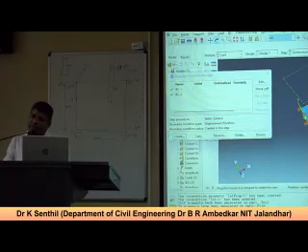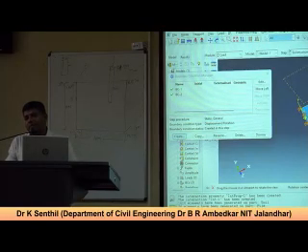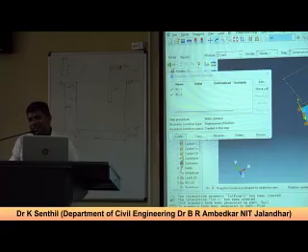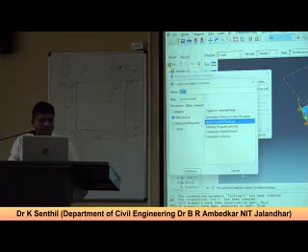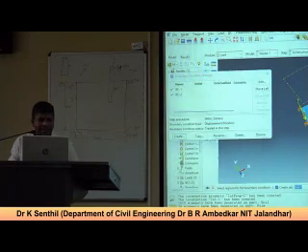No, we have already defined the mass. No, we haven't. You only defined the force. Okay, and you define it in the vertical. That is the external force coming from the superstructure. The only way you get these earthquake-related problems to get the inertial force, you need to create a lumped mass on it.